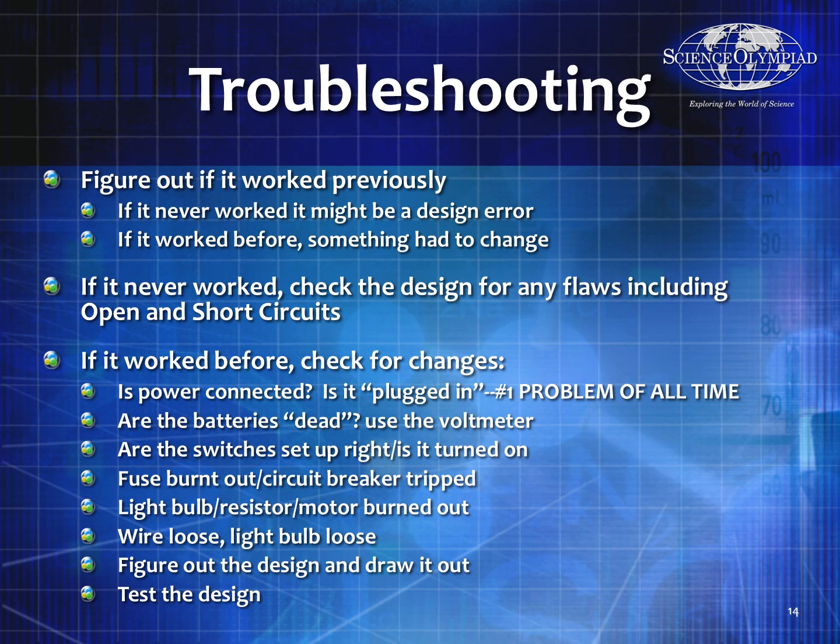And then you look up and you say, well, I guess the light bulb is burned out, so you go replace the light bulb. But a lot of times it could be loose. Sometimes the light bulb is loose, sometimes the wiring is loose, sometimes the connectors are loose. And by the way, these are all common things that I might do for my troubleshooting hands-on activity. I may pull one wire out and see if you can figure out which wire was pulled out. I might unscrew the light bulb slightly. Okay? Only after you've checked all the simple stuff.